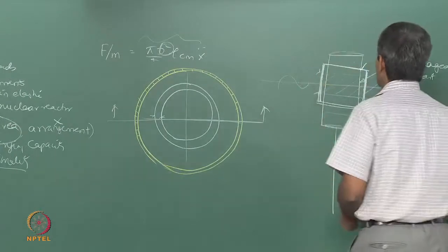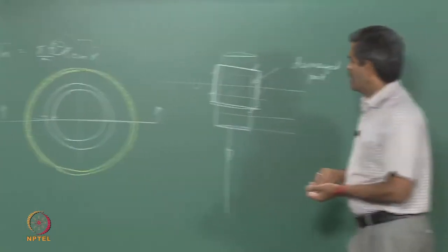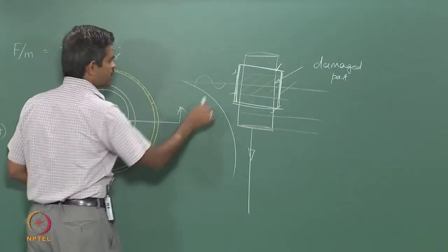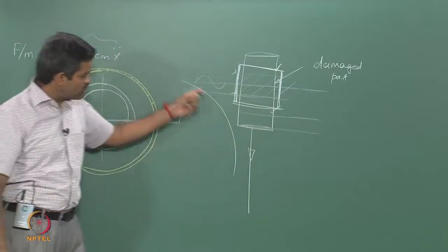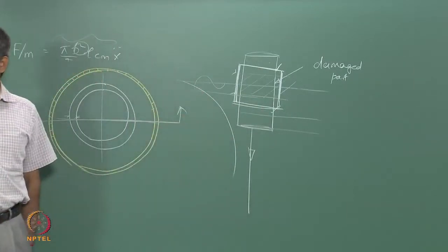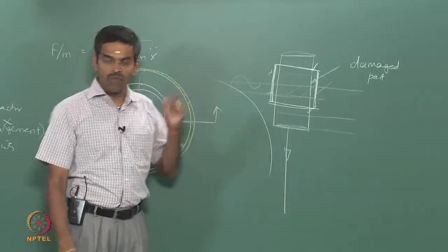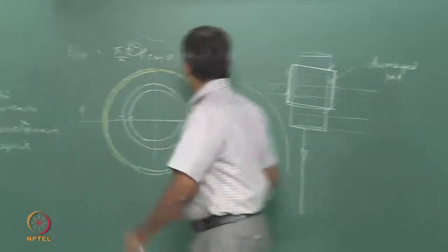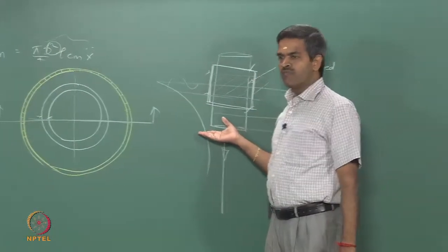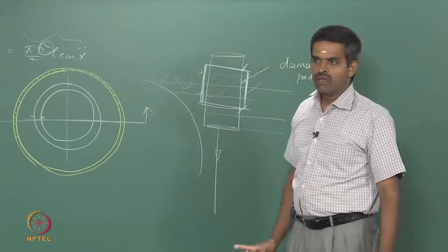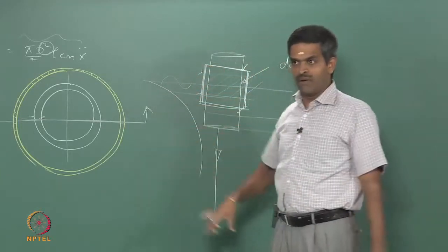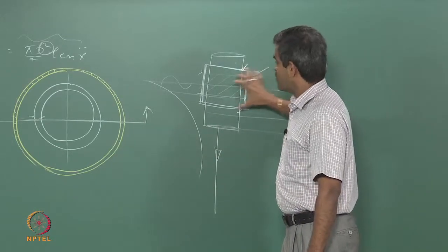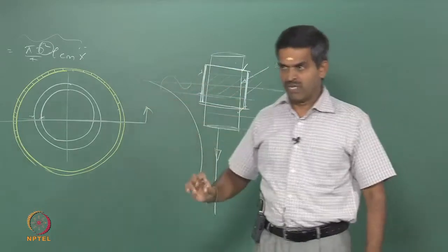The second reason is, we all know from hydrodynamics so far, the force plot varies non-linearly and it is maximum near the free surface, and as it goes down and down it practically becomes 0. Okay? Therefore, if I am talking about force reduction, I must always supply that mechanism only at the point where the force is maximum. If I keep on doing it for the entire length where there is no force, in fact I am not doing any reduction at all, because there is no force at all. So, I must apply only in that segment where the reduction is maximum. Therefore, the second reason why I am putting the cover only at this zone is that I want to aim at the force reduction with a unique approach in this case. That is what I already said.